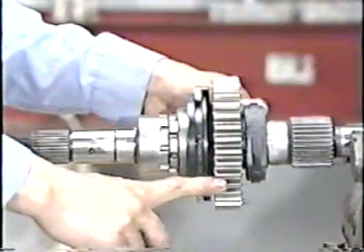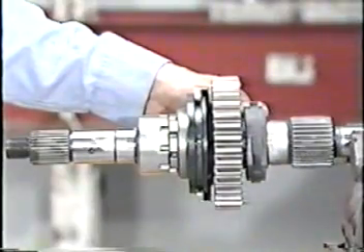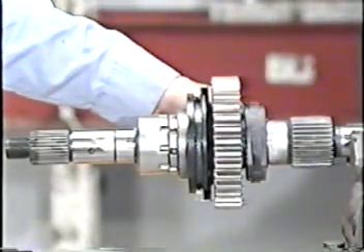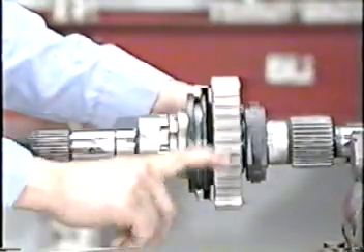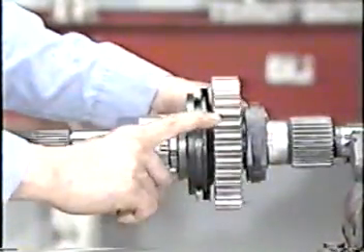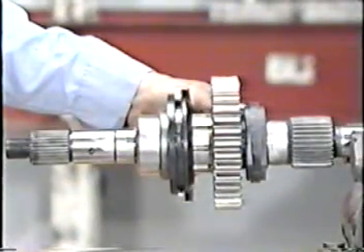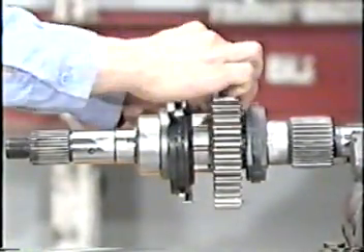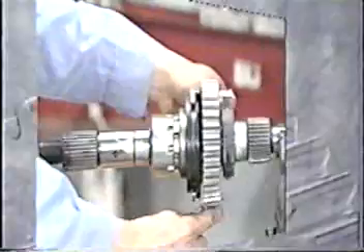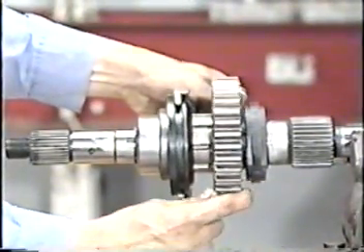In two-wheel drive, the input shaft is locked to the rear output shaft, supplying power to the rear axle. The drive sprocket on the rear output shaft freewheels, and no power flows to the front axle. In four-wheel drive, a lock-up collar controlled by the lock-up shift fork assembly slides forward to engage the drive sprocket and shift collar hub, locking the drive sprocket to the rear shaft. The chain then drives the front output shaft, powering the front axle.